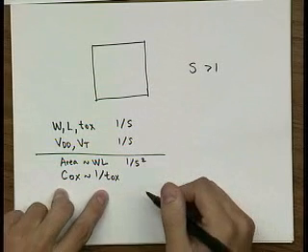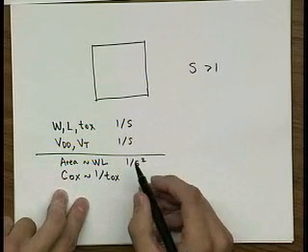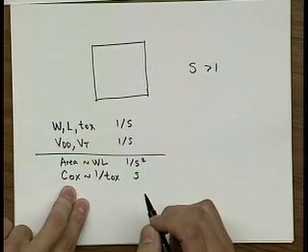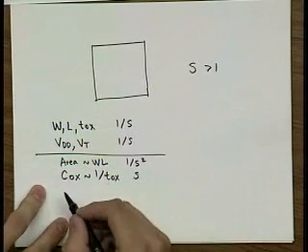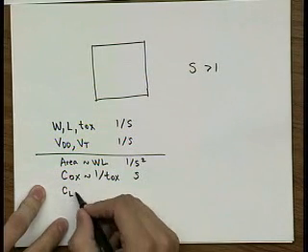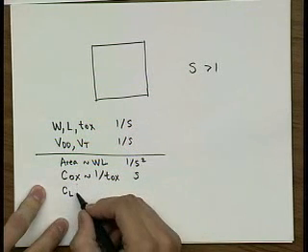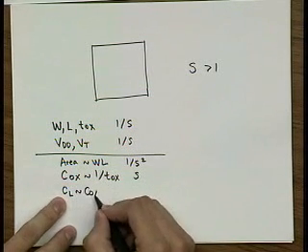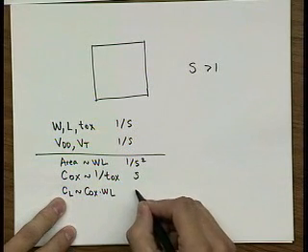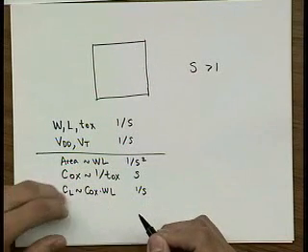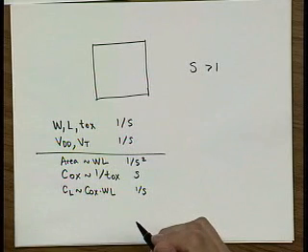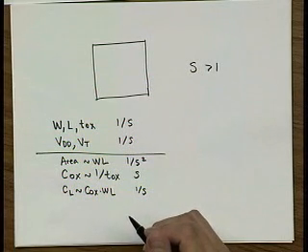So if T_ox goes down, then my capacitance per unit area goes up by a factor of S. The same happens for the load capacitance. This is just the capacitance per unit area, so the load capacitance is proportional to the capacitance per unit area times the area, and then you end up with the scaling factor 1 over S. So the capacitance that you need to drive decreases by a factor of 1 over S.